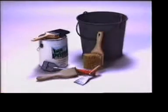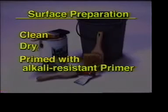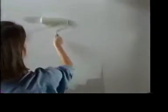The condition and preparation of the surface to be coated is key to ensuring that your coating performs as it should. The surface should be clean and dry, and primed with an alkali-resistant primer. The quality of and care with which a primer is applied can have huge effects on the lime burn of the top coat paint. Check with your paint supplier for primer recommendations. Remember, the longer the cement-based substrate has cured, and/or the better it is sealed with primer, the more the risk of lime burn is reduced.